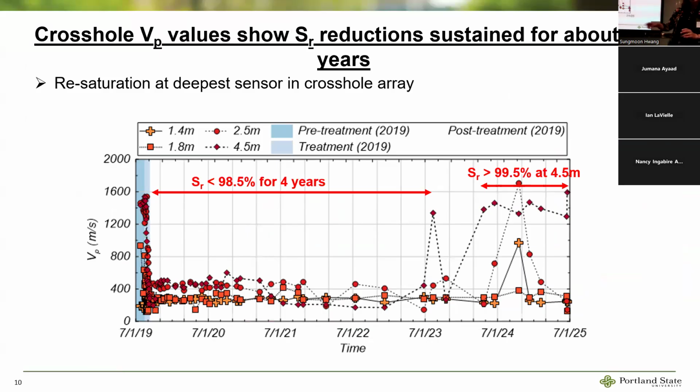Oh, like how it started to come up in about the summer, instead of in the wet season? What's your thought process behind that? So I think that as far as water table fluctuations, we've looked at that, because the water table at the site floods in the winter and goes down to about 1.8 meters below the ground surface in the summer. So there's this fluctuation happening.